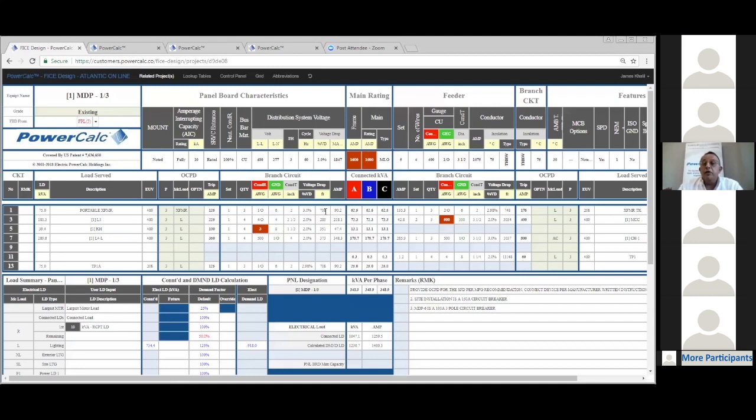Okay, so the system is already doing the required calculations based on the recommendation automatically for you. You really don't have to do anything. Now you can adjust that as you go in your design. If you're not happy with the 1,847 feet, say it's longer or shorter, you can always adjust that, and then the system will go ahead and adjust the feeder for you to maintain that particular voltage drop. Okay, so this is in a nutshell today.